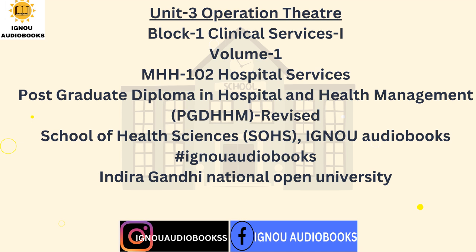If possible, operation theatres should have their own wing, an independent low building. This will help in future expansion of operation theatre complex without disturbance to other departments of the hospital. Operation theatres require more height, approximately 4.2 meters, because of air conditioning requirement of a modern OT. It is therefore felt, if there is only one multi-story building of a hospital, then OT should be located on the top floor of the building because of ease of providing more height.